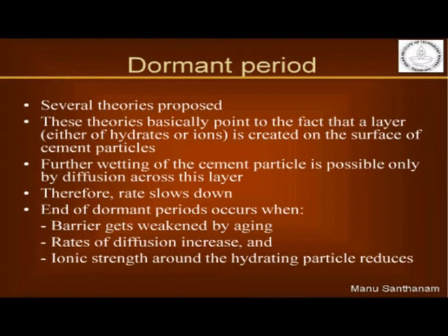So many different operations have to happen without the cement actually setting. Okay, so this dormant period is very crucial because the duration of this dormant period usually tells you the duration of the setting period, how long actually it takes for the cement to set. So this dormant period is very crucial from the point of view of application of the cement in concrete.